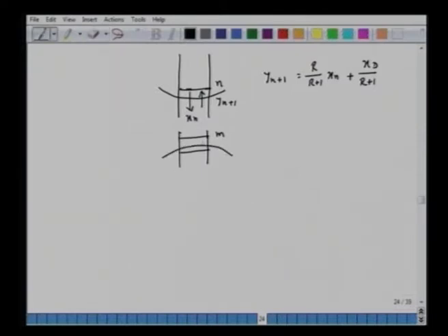and we took this envelope like this. The stream which arrives here is Ym plus 1. The stream which is arriving here is Xm. This flow rate here is L bar, this flow rate here is G bar, and this liquid L bar we know is the bottom product W, and the vapor, which is nothing but pure steam, is G bar. So we have this Y at NP plus 1 equal to 0. So there is no reboiler here. So what happens to our balance here?